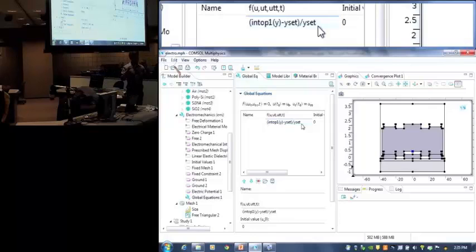So if you're adding a global constraint which has all these variables of the order of 10 power minus 9, along with a few other equations which have different orders of magnitude, then it can be numerically difficult convergence-wise. Internally, Comsol will scale the finite element model so that the magnitudes of dependent variables correspond to almost 1, just for convergence reasons.